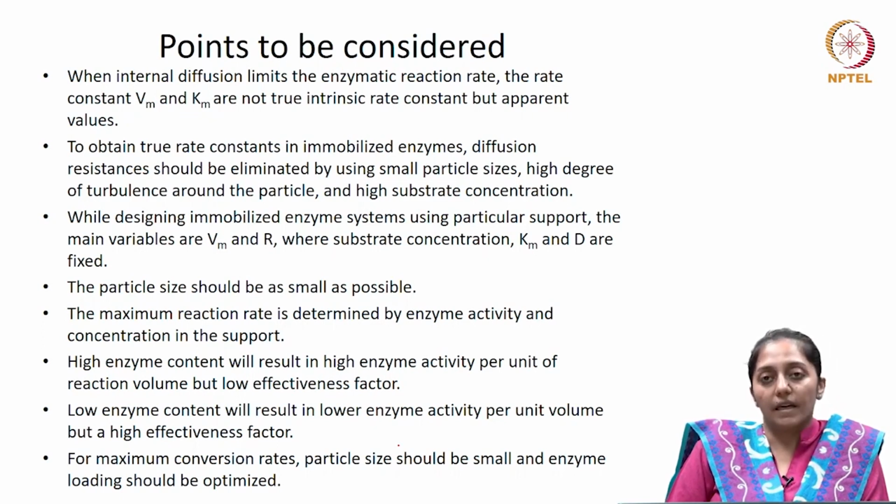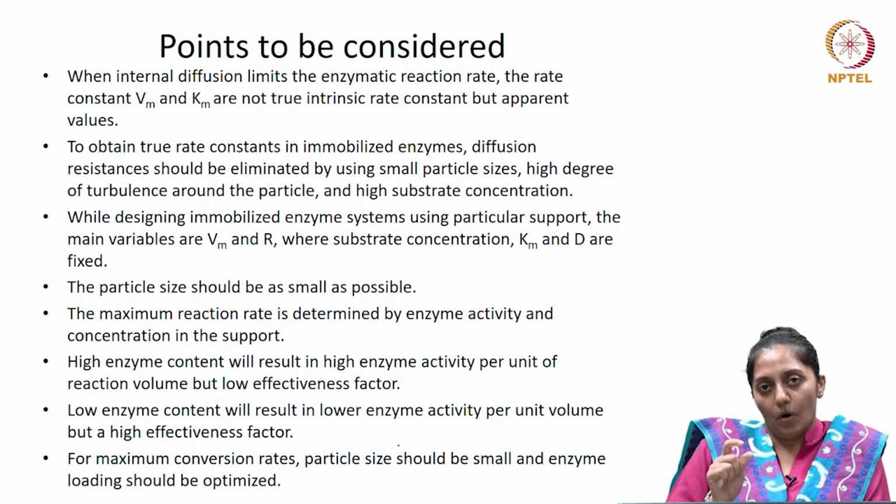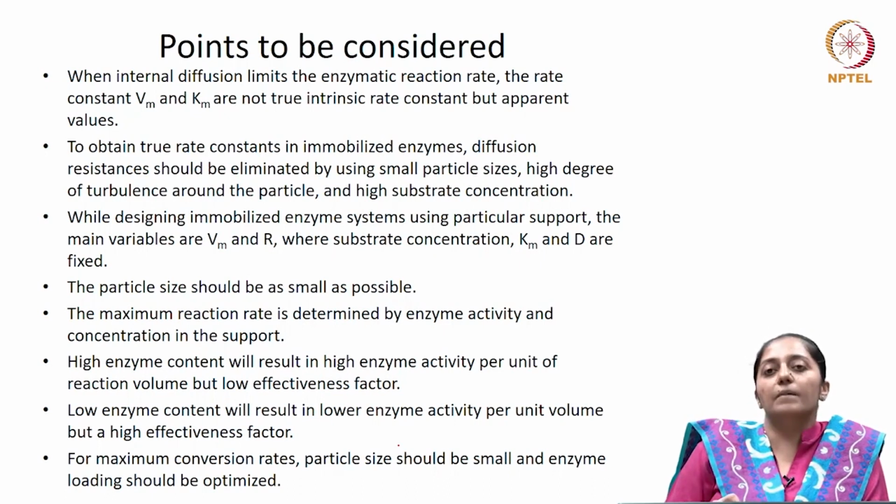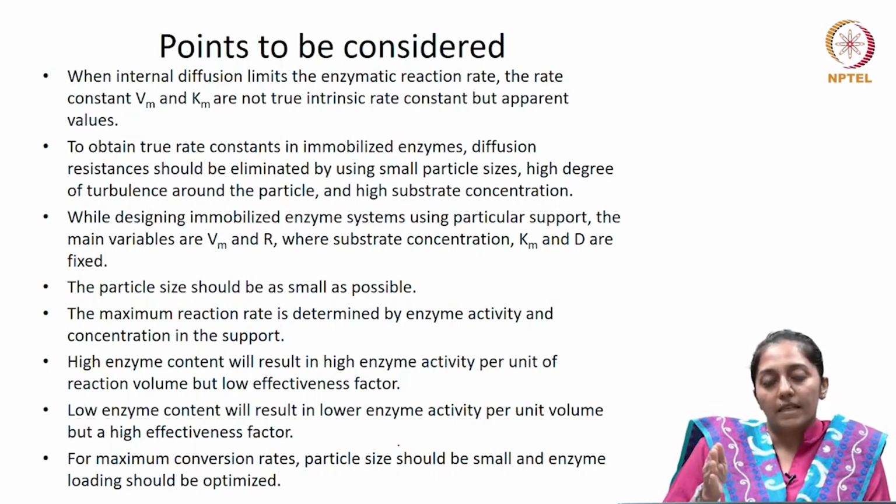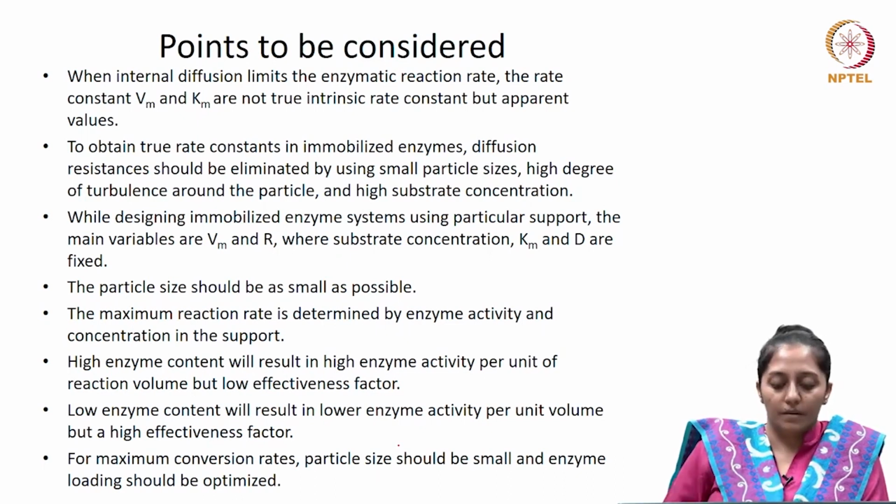So, for maximum reaction rates, what should one do? The particle size should be kept small and the enzyme loading should be optimized, so that although the enzyme activity per unit volume is being optimized, the size of the particle is being designed so that all the substrate is able to reach and get converted with the enzymes present in the inner core.